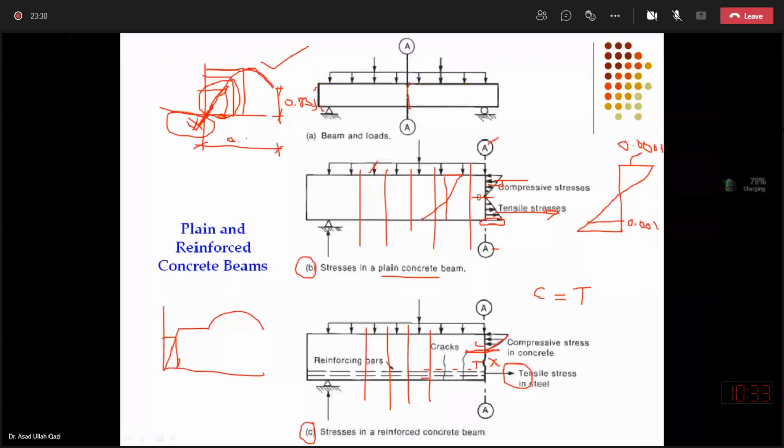So normal strength concretes, if you test them in the laboratory and measure the stress and strain relationship, it is quite possible that you get the softening at 85% of the peak corresponding to a strain which is 0.006 or even bigger.